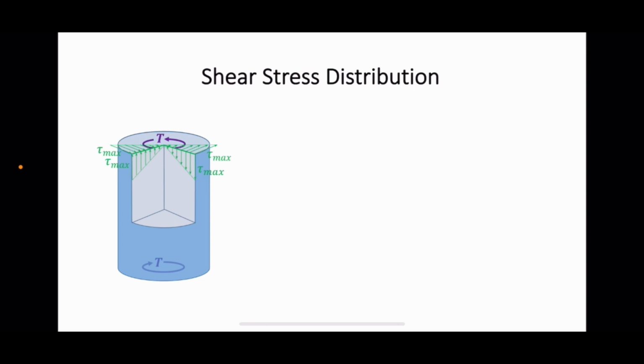To help you have a much better understanding of the topic, let us visualize the stress on the following volume element. Here will be the result if we zoom in. You can see that the two elements are subjected to pure shear stress. As the red element is at the boundary of the shaft, it is subjected to the maximum shear stress.